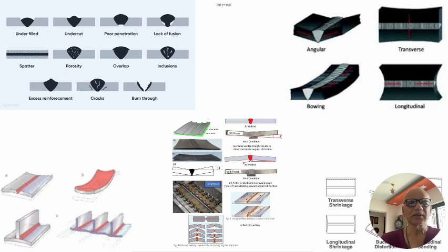The last defect, the burn through, is mainly because of excessive current, larger gap, lower thicknesses, and improper welding speeds. So there are many reasons for burn through, and if you do not have good control over your welding, burn throughs are unavoidable. And once you have a burn through, you really make a larger root gap in that area, and then to fill it up is a real trick.